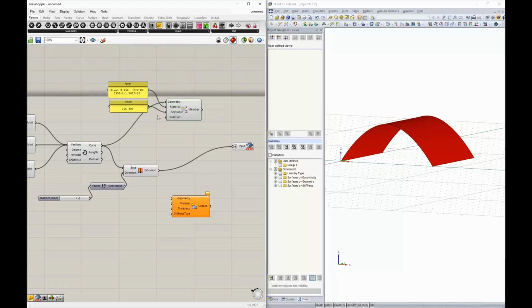Of course, we can change the rotation of a member. We can do it again maybe using a panel. Let's say we enter values from 0 to 90 degree. So here I can switch between the values 0 and 90. I could theoretically connect now this slider with the rotation. There's just a small issue. We expect the rotation in radians. For me, this is now degree.